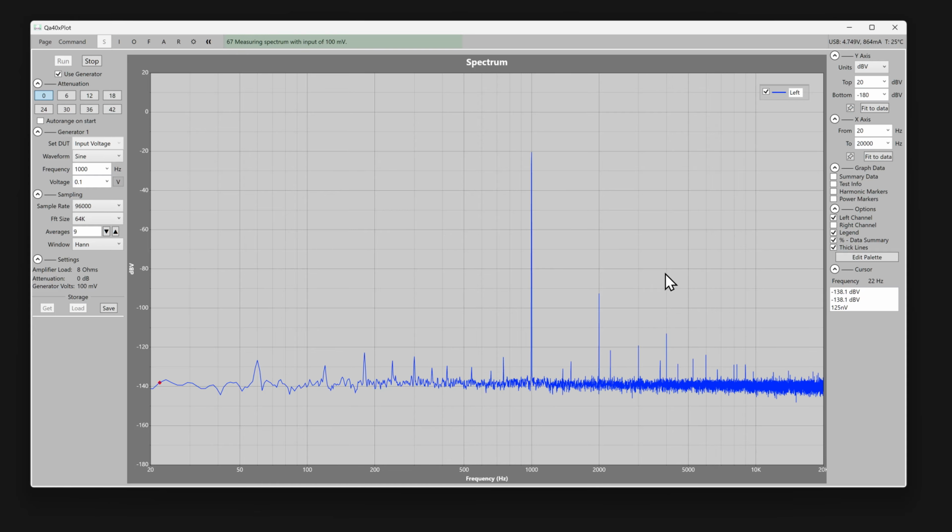So this is a pretty good analysis. And as an example, I have this really nice preamplifier that I'm testing. This is the preamplifier output. I've set the gain in it to approximately 1, so it's about 1/10 of a volt in and 1/10 of a volt out. Now, I have replaced all the caps in the left channel, but not the right channel. And so when you look at the two spectrums, they are pretty different.